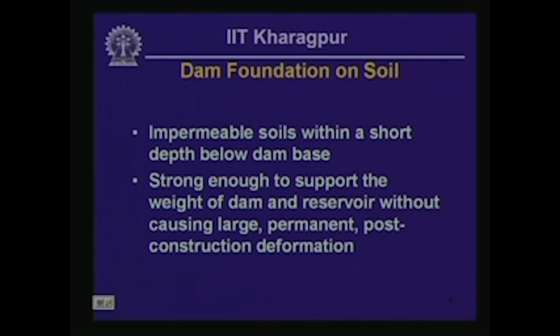The soils underlying the dam need to be impermeable, or impermeable soils need to be present within a reasonable depth underneath the base of the dam, and the soil should be strong enough to support the weight of the dam and reservoir without causing large permanent deformation. These are the aspects to consider when selecting a soil site for constructing a dam.